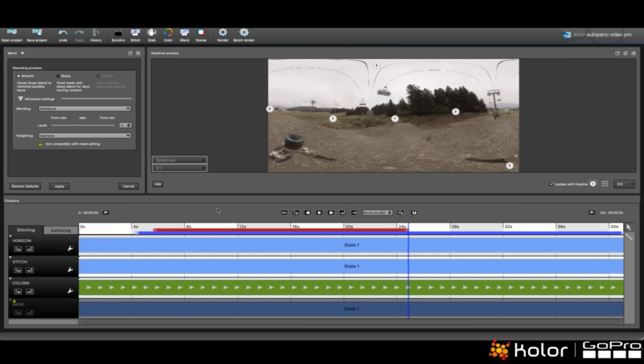Well, actually, if you just press F here, you're going to be matching the size of your selection with the size of your render area. So that's F. F will allow you to do that. Now, let's say you are working on a small area and you want to match the size of the render area to your selection area. Well, Shift F will allow you to change that and to change the size of your area.